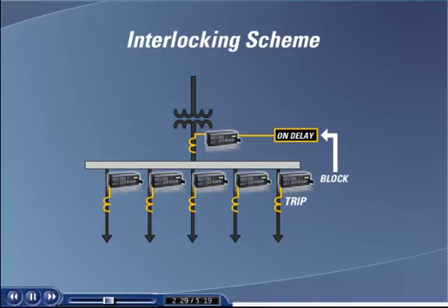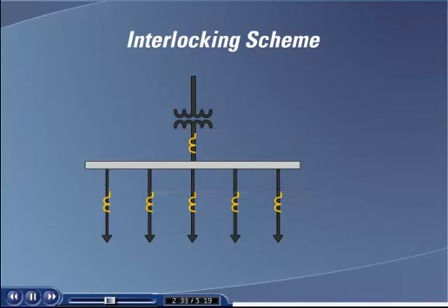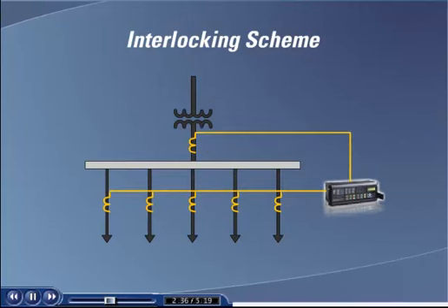When using microprocessor-based multifunctional relays, it becomes possible to integrate all the required OC functions in one or very few relays, thus not only reducing wiring and coordination time, but also speeding up the operation of the scheme.